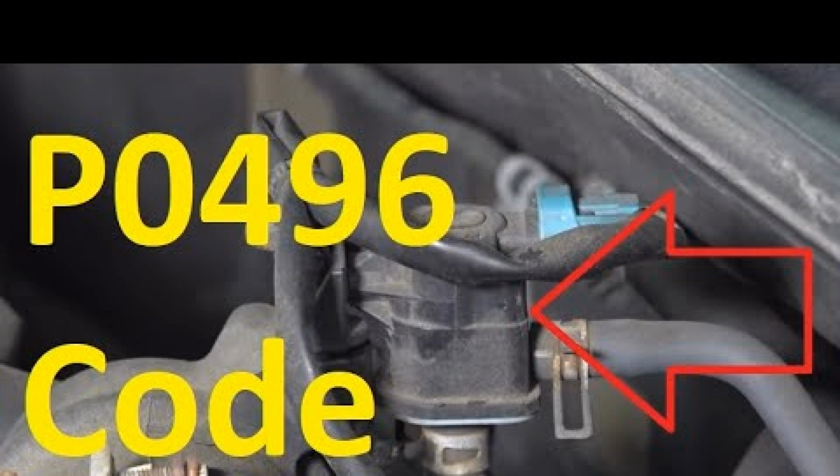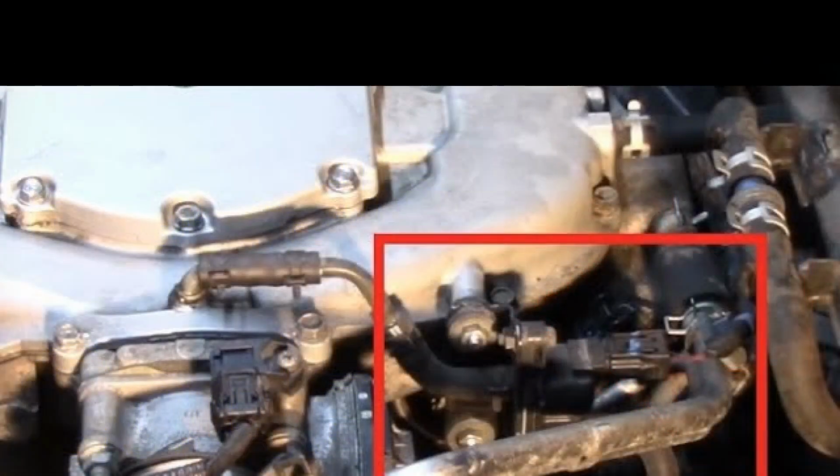If you see P0496 on your scanner, it simply means that your car's computer thinks the EVAP system is venting fuel vapors when it shouldn't be. Older systems, pre-OBD2, only purged the tank when the engine was running above idle and warm. OBD2 systems can purge the tank at any time the engine is running, even at idle. However, the ECM or PCM knows that it should see a slight change in the fuel setting when the purge is triggered, and looks for this. Some vehicles use leak detection pumps, which provide an additional input. In short, if the ECM or PCM detects an uncommanded purge flow, it triggers code P0496.